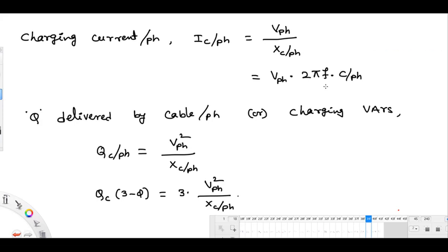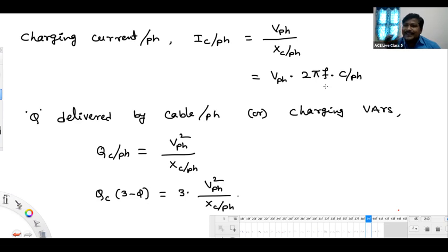But that reactive power circulation is due to the capacitive element. In designing, I don't say it's capacitive. It's a battery you are keeping on one side of the voltage source converter. On the other side you are getting AC supply, just like an inverter action. But we are not supplying any real power.